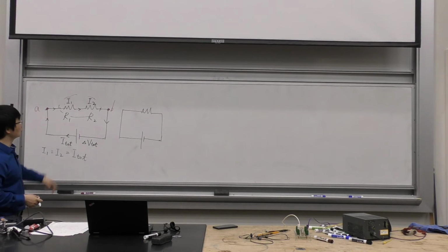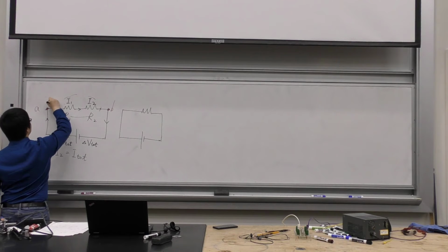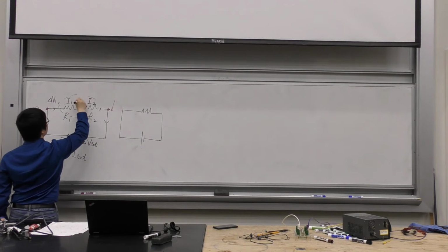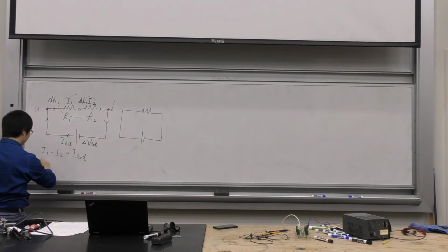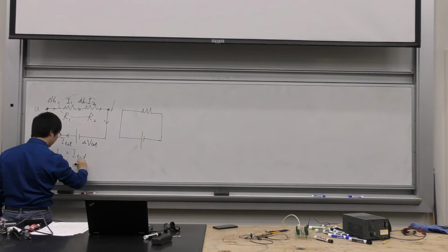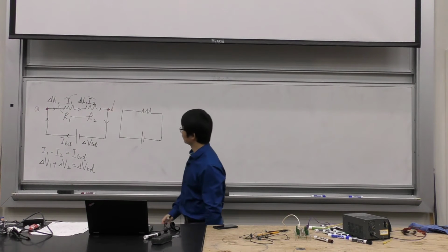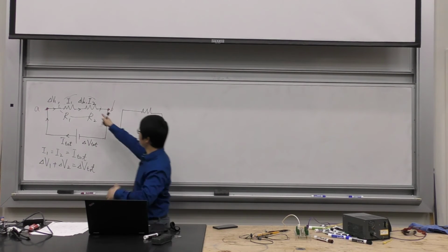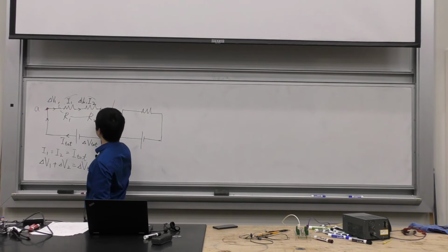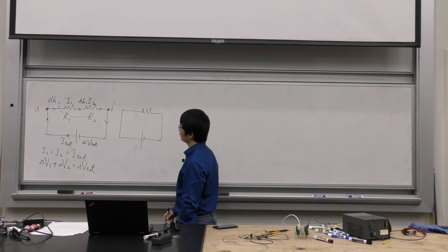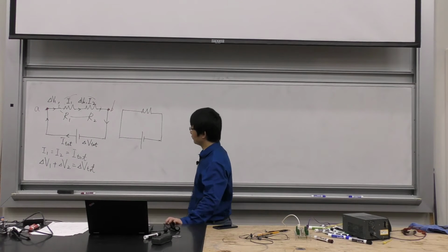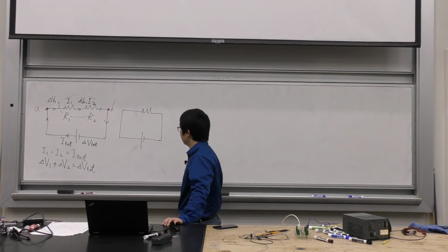And then if you add these two voltages together, you call them V1 and V2, you actually get the total. So each of them is just going to get part of the voltage from the circuit, okay? Because this combination is connected to A and B, so they will get the total voltage from the battery. But each of them is not directly connected to A and B, so they only get part of that.